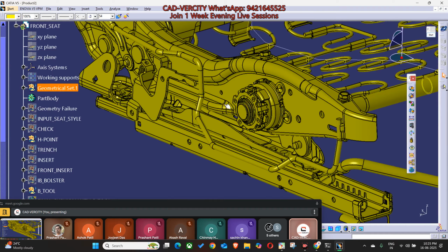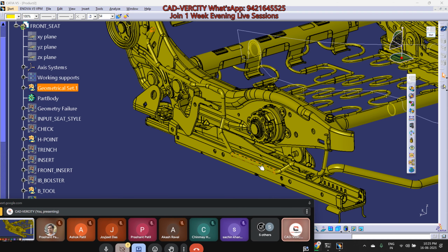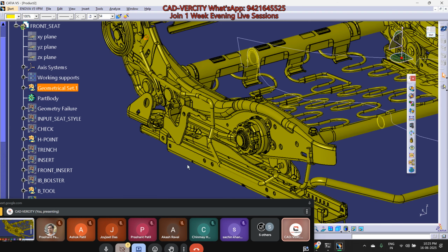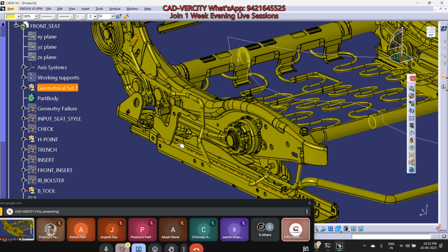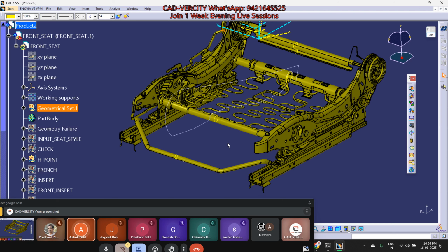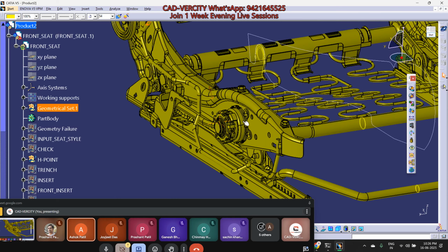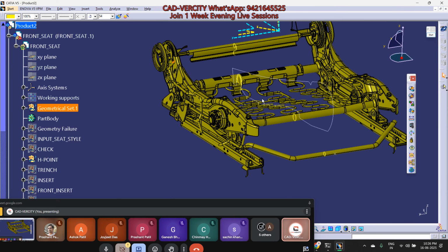So what is the purpose of the wire? The purpose of the wire is that we will take support for the side cover. We will lock the side cover on this wire. Got it, Sachin, Raja, Ganesh? That's why we have learned the design of hook and locator. Hook is very important for this. This wire also should avoid clash with foam. Previously we discussed this wire. We should avoid clash. See, there should be no clash with foam. That's it.